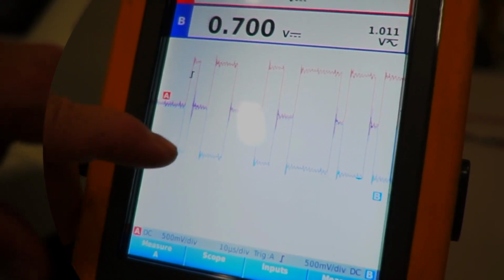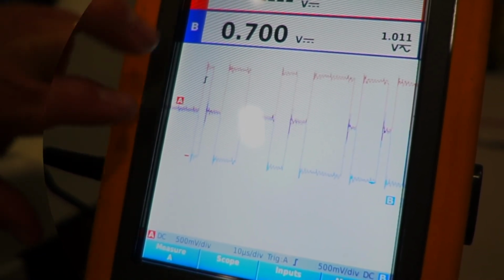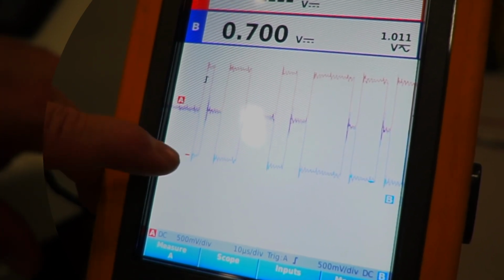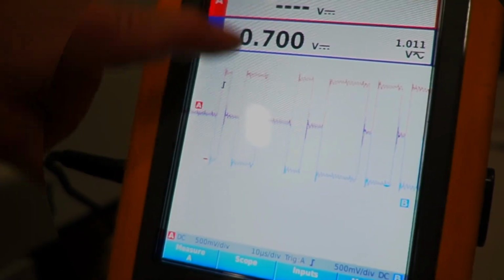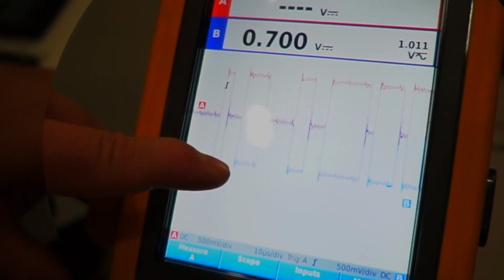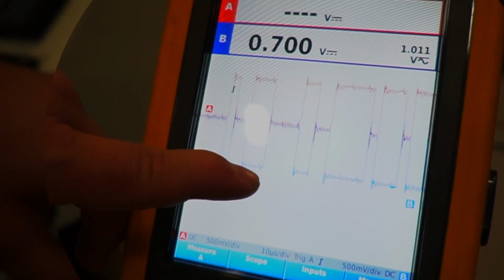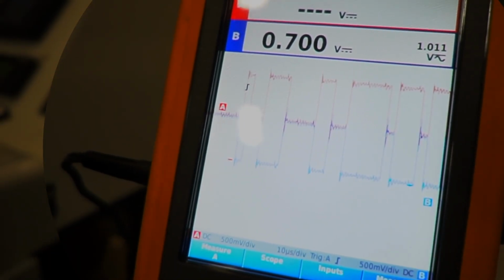This window is about 8 microseconds long, so that would be 2 bits where the differential is 0, so it would read that as 2 ones. So it would read this as 0, 1, 1, and then the differential in this box is also high again, so this would be 0, 1, 1, 0, 0, 0, and then they go back together, so 1, 1, 1. Hey, we're talking binary language here.